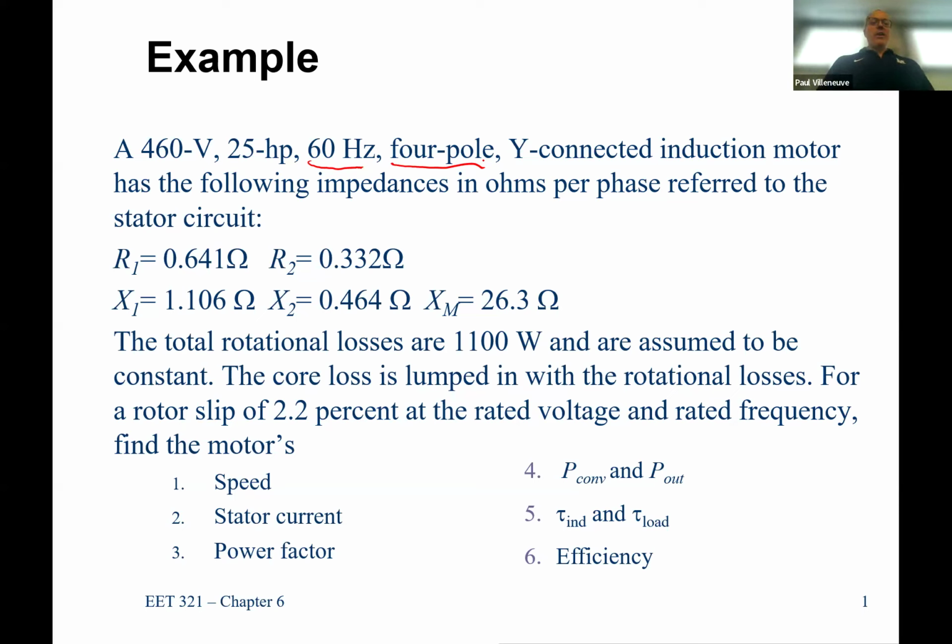We also know that it's 460 volt and Y connected. That's important for us because we've got to calculate the stator current. So knowing 460 and that it's Y connected is relatively important. It's an induction motor, so we want to develop an equivalent circuit. Again, we're looking at circuit analysis, so the induction motor part tells us what the equivalent circuit model is.